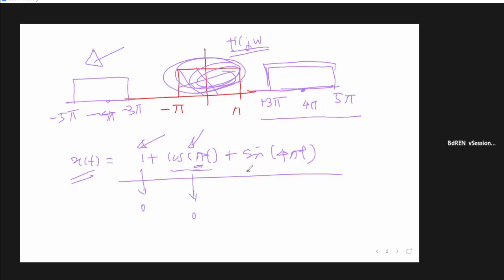Then you see that sine 4 pi t is within the bandwidth of your filter. Then your output will be this, okay? You are getting your output sine 4 pi t. So this is very simple. You need not solve your problem rigorously. Simple intuition can give you some solutions, but practice is needed. So some other examples are there. Try to solve this, okay? Very similar to this one, okay?